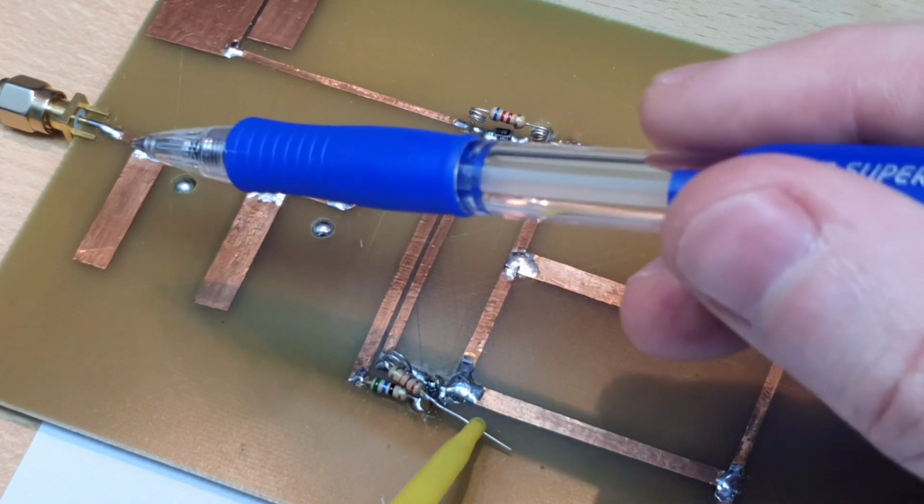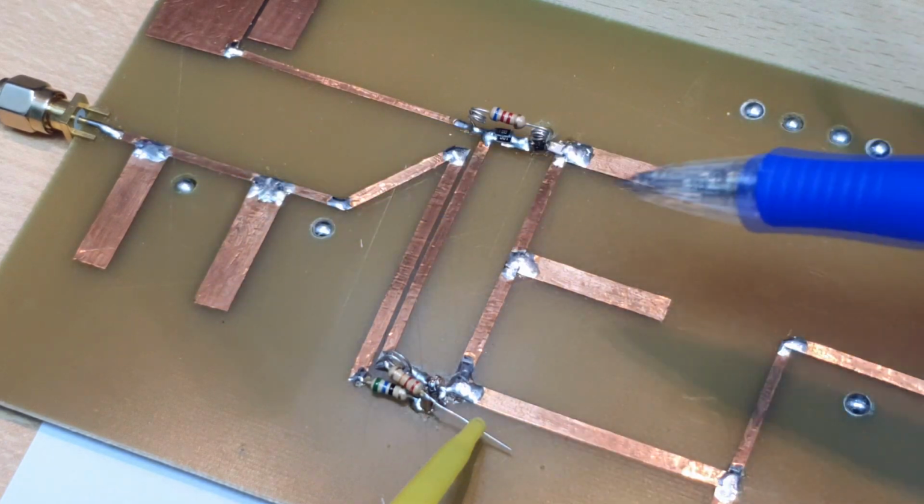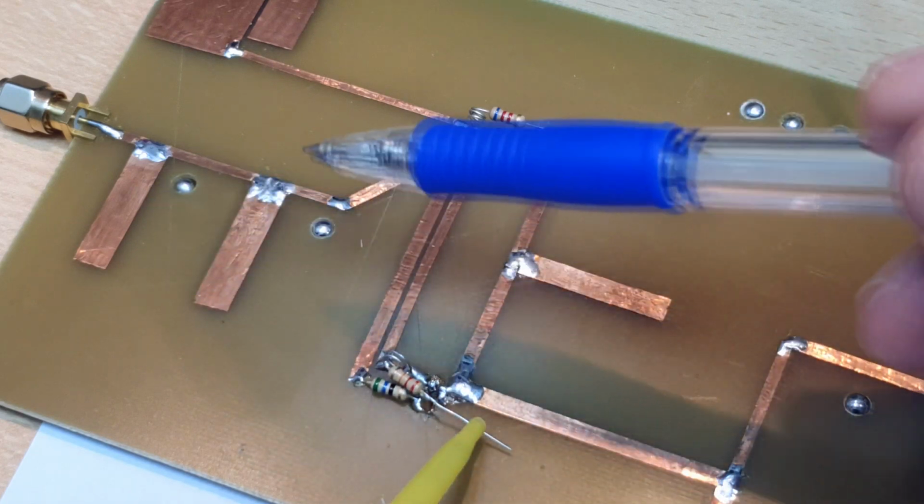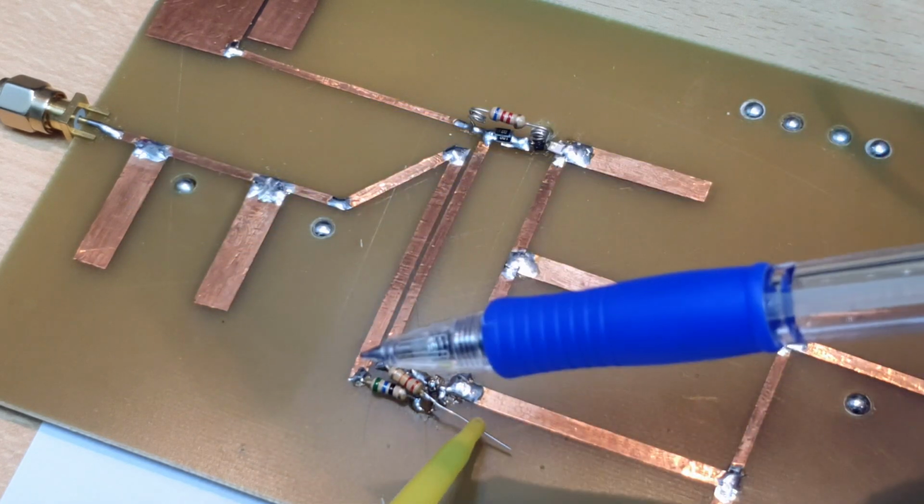This is why the output is so clean, guys, because we have the input duplexer and we also have this output notch filter at the input frequency. This topology was used a lot in old vacuum tube circuits. This was the way to frequency divide a signal. Today, almost all the applications of frequency dividing is made using static logic circuits, flip-flops and counters.